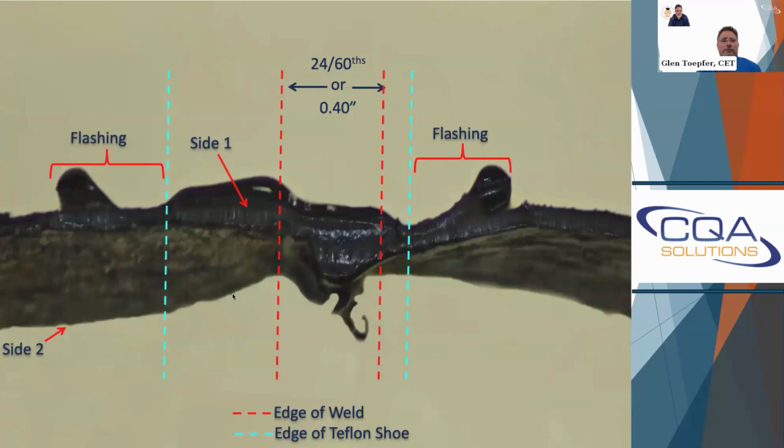If you look at extrusion, one of the challenges with extrusion, well, there's a couple of them. One is that your weld, per the ASTM and the guidelines, really is that you only count what is equivalent to the sheet thickness of the extrusion weld. So if it's a 40 mil sheet, you should have 40 mil of extrudate. And if it's any less than that, it's not counted. So that's where you cut off your boundary there.